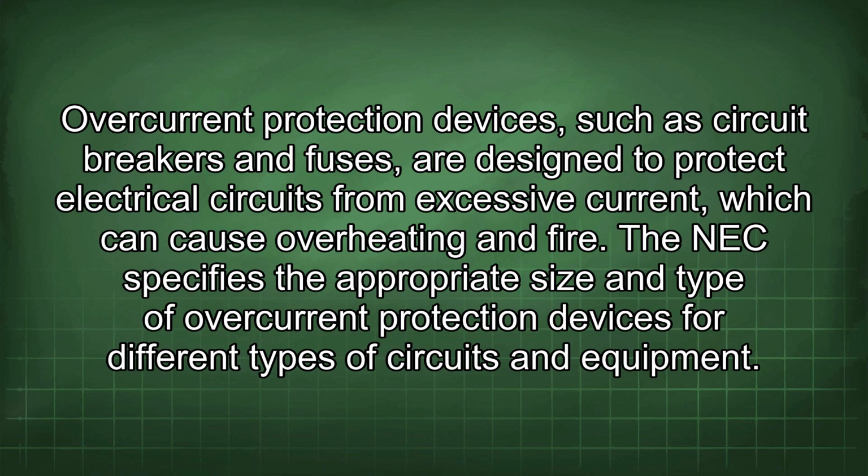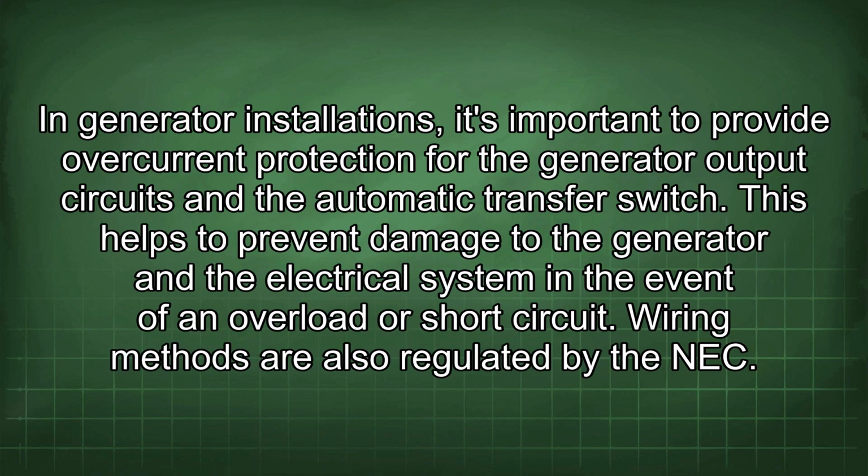The NEC specifies the appropriate size and type of overcurrent protection devices for different types of circuits and equipment. In generator installations, it's important to provide overcurrent protection for the generator output circuits and the automatic transfer switch. This helps to prevent damage to the generator and the electrical system in the event of an overload or short circuit.